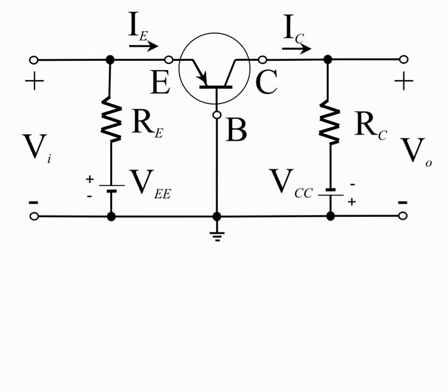So with this we see that the positive is connected to the P and the negative of the voltage source is connected to the N. This makes the emitter base junction forward biased, and across this junction the forward biasing is applied. So the voltage across this emitter base junction would be called VBE. VEB actually, that will be applied across this junction.